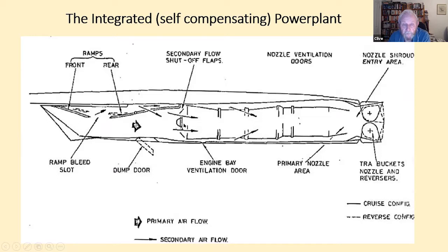If the bleed increases, generally speaking, the intake pressure increases. So a decrease in intake efficiency is compensated by the closed loop effect, if you like. And the same is true if you go through the argument if the engine has a hiccup: again, the things self-compensate. So you don't have the sensitivity that you do on some of the other designs. And that has helped a lot, frankly.